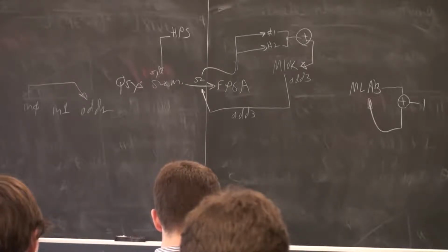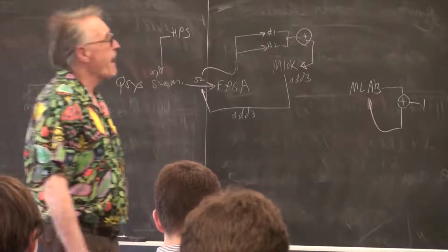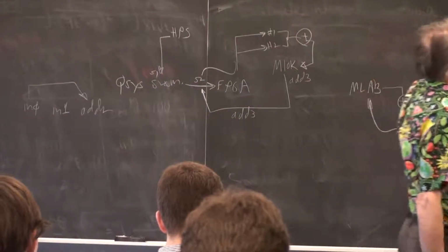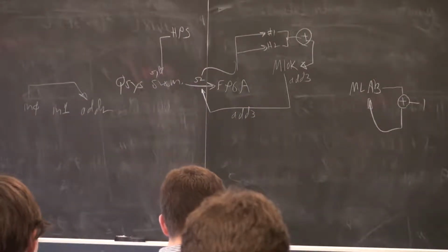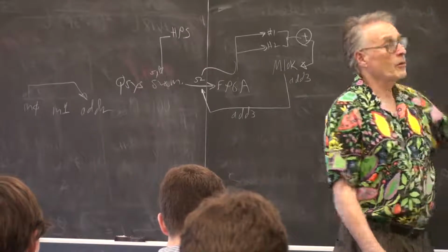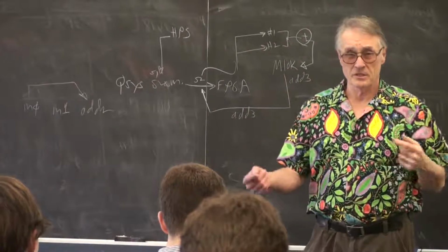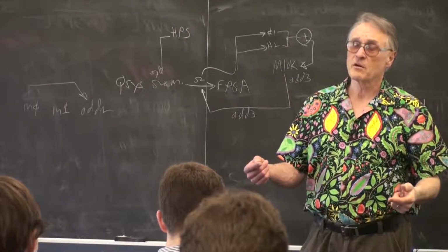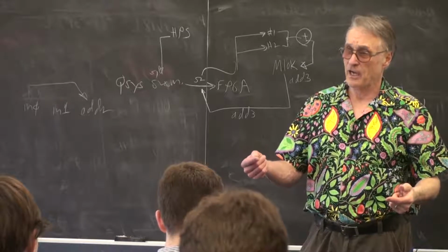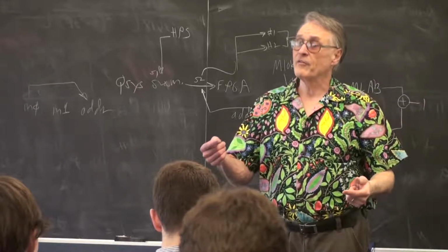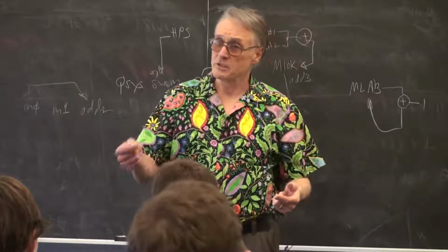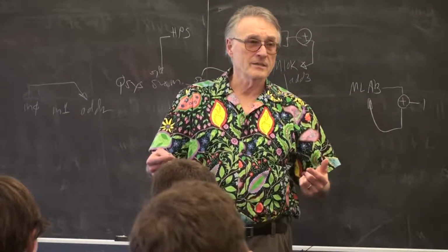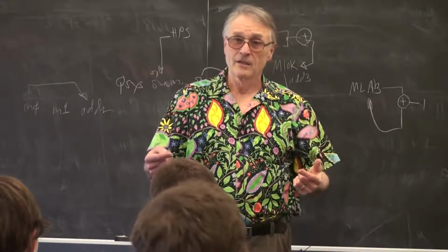8 slots of the memory. Address 0, address 1, I typed in a 5. Address 3, address 2, I typed in a 3. Then I gave it the command 110, which writes a 1 into position 0. Position 0 is the handshake. If the FPGA sees a 1 in position 0, it says, new data.